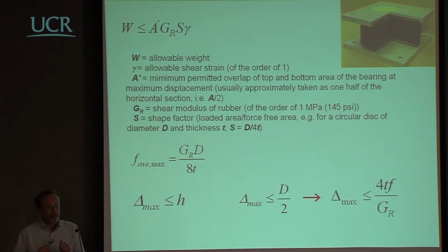So what I'm trying to say is that this is exactly the reason why they put steel plates in a rubber bearing. It's just to increase the vertical capacity and consequently to be able to have relatively tall devices without reducing their vertical capacity.